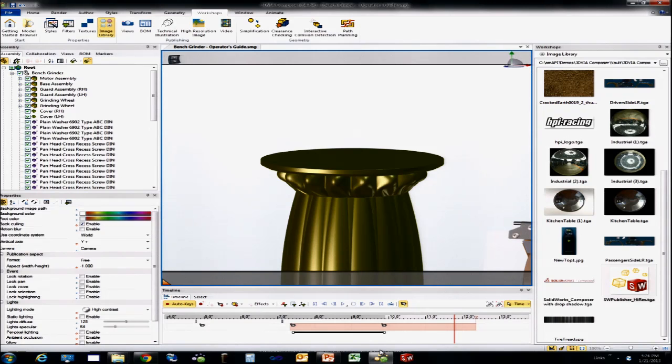And to be sure, in this particular case, there are filters. You can filter on specific keyframes. If you've selected a particular object, you can filter on that selected object and perhaps its location keyframes. So if you've got a fairly complex timeline, you can filter on just that one and then make the same kind of adjustments just for that component and not mess with everything else around it.